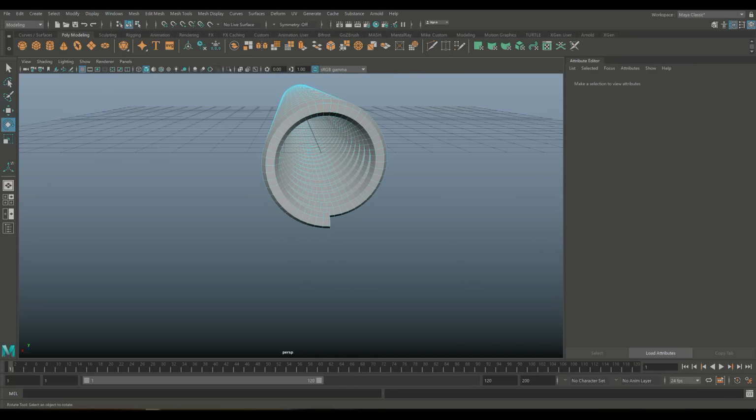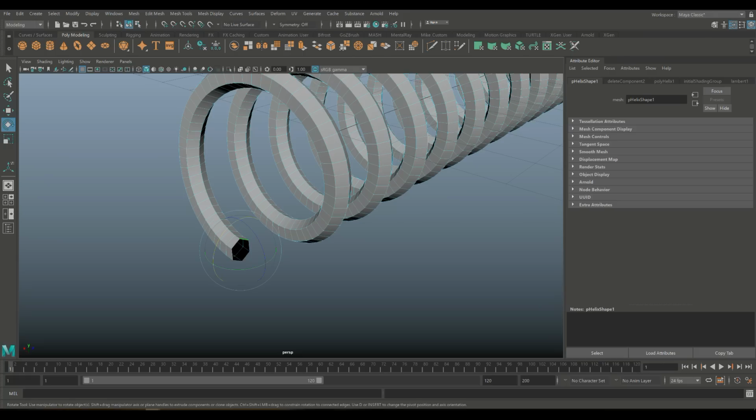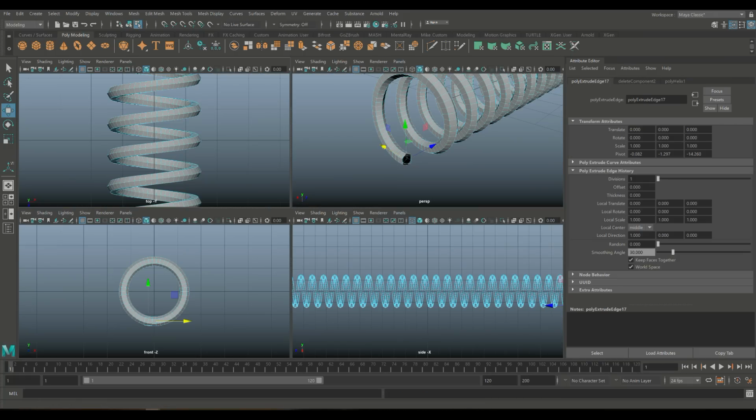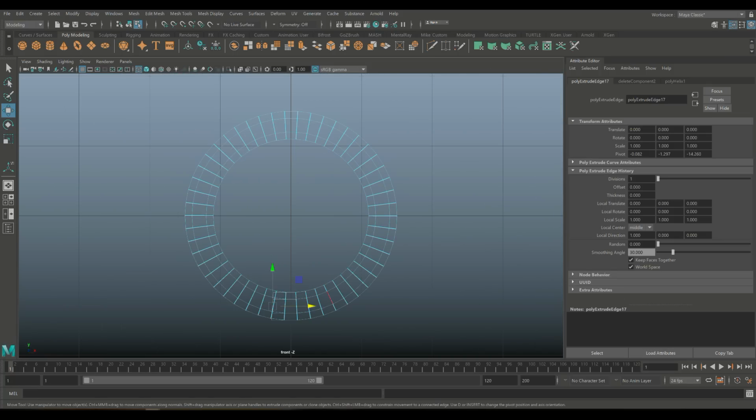So if we delete that, we can then go in, right click at the edge, double click, Control E to extrude, W to pull out, and let's just make an extension here. Let's hit 4, G to repeat, W to pull out, G and W, G and W.